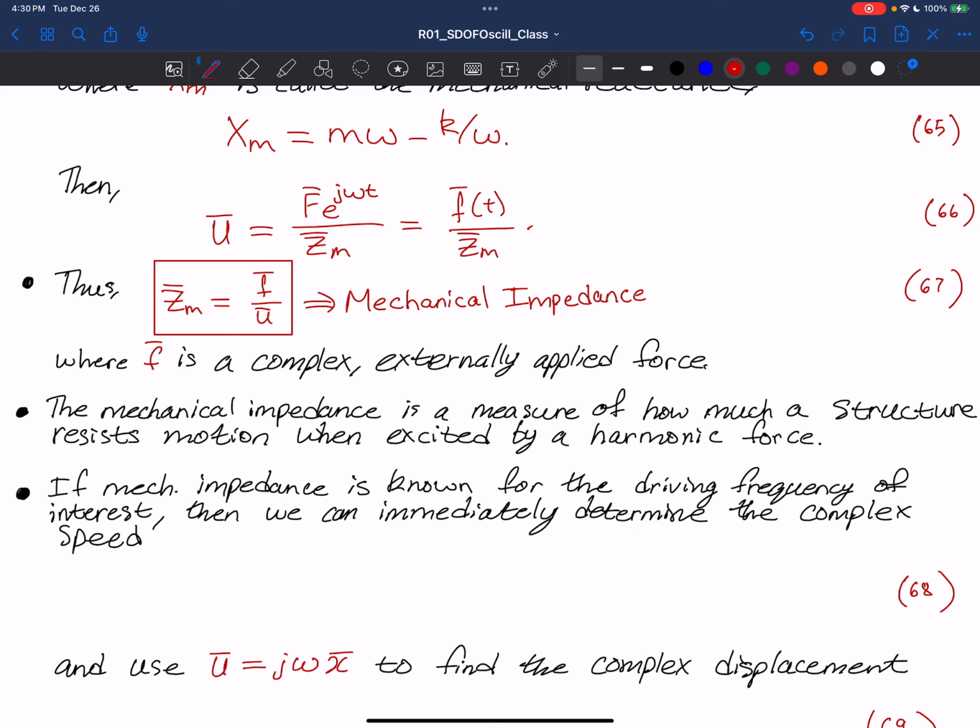We will end up using the concept of mechanical impedance later on when we deal with acoustics, particularly when we look at pipe systems which have an oscillating driver involved that creates waves that propagate down the pipe. In that case, we'll be looking at how the mechanical impedance couples to the acoustic impedance.